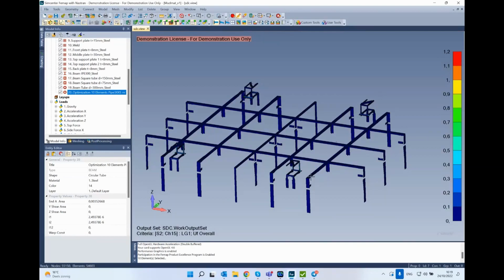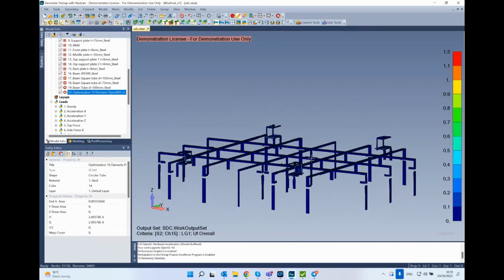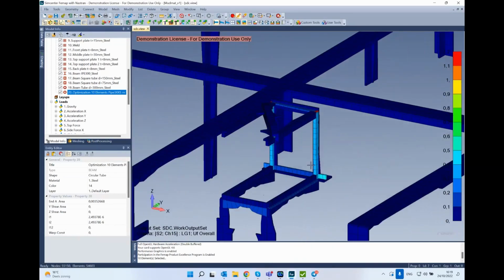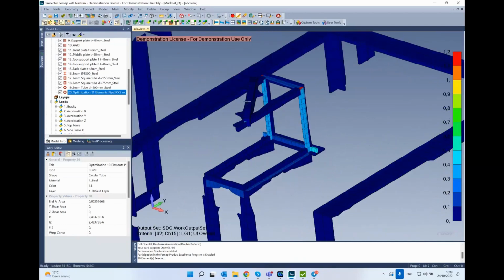And we see that for this model, for these particular stresses, it's all okay. We are almost not having any significant results, except these ones where it's around 0.3, 0.4. So we can save some material, the model is strong enough. We can reduce the size of the weld. So let's do that.